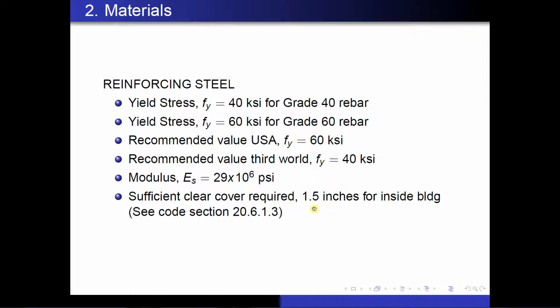In this way, the concrete is not only taking compressive loads, but it is also providing some protection to that reinforcement, protection from erosion and corrosion and things like that. So it's important to provide adequate clear cover, and it is even a code requirement, and you can see more information about that in the code in section 20.6.1.3.